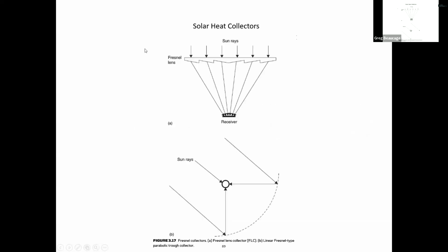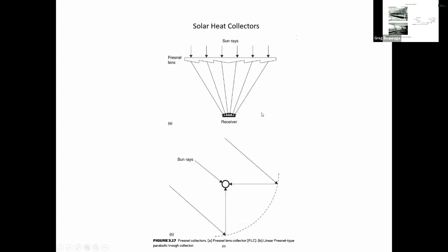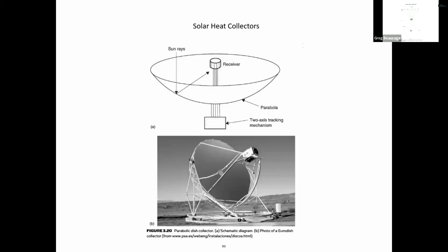So that shows a cross section of that evacuated tube. But then there are focus solar collectors. This Euro dish has what's called a Stirling engine up here, so it makes electricity from a heat engine. You can do it with this parabolic reflector that has a heliostat that tracks the sun. It can rotate in a circle and it can tilt, so it can go anywhere the sun goes.